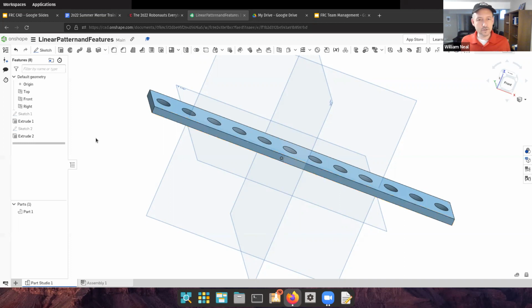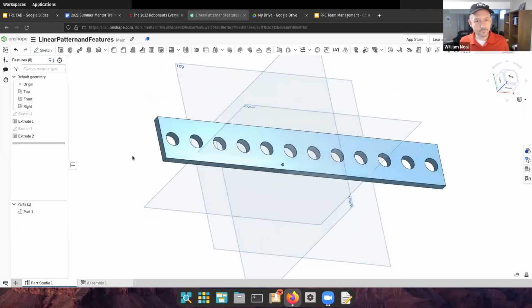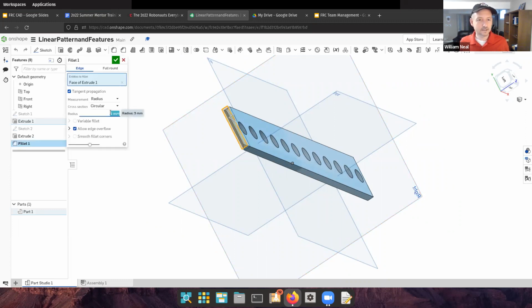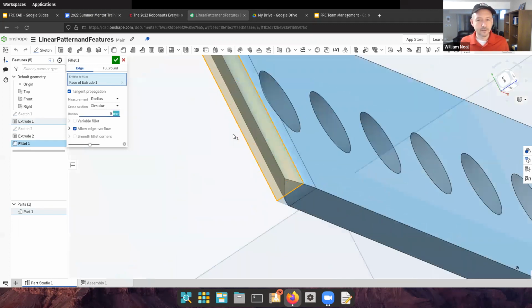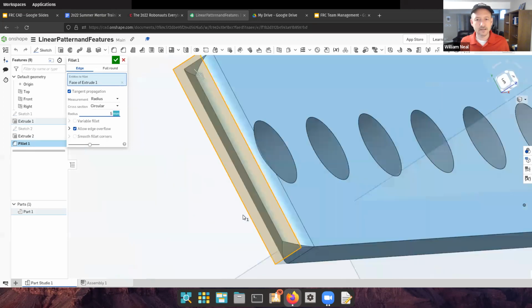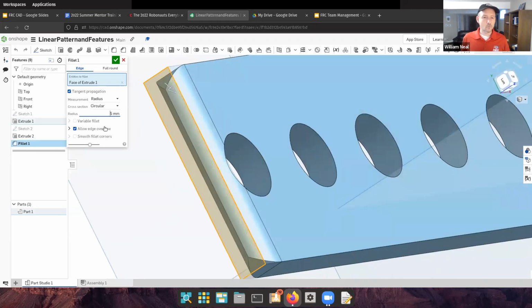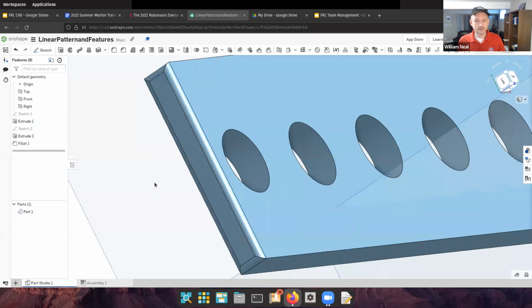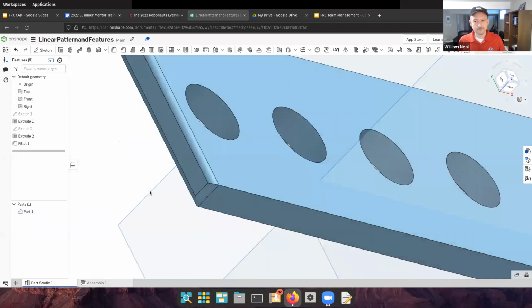If I choose, for example, one side of my bar, let's fillet it. And we'll say that the fillet is a certain amount. You see, it's cutting it off a little. Each edge is kind of sliced off. I'm going to make it just a 1 millimeter fillet. And you can see a kind of a rounding on the bar here. There we go. There, I filleted the edge.